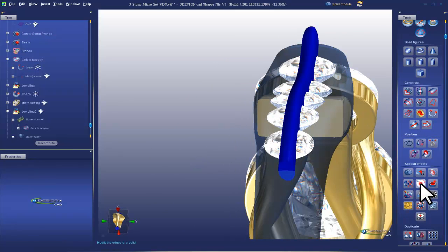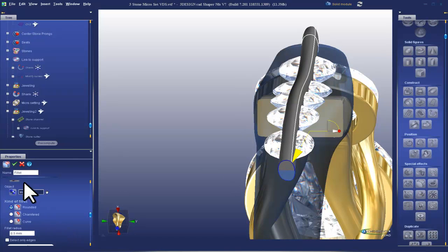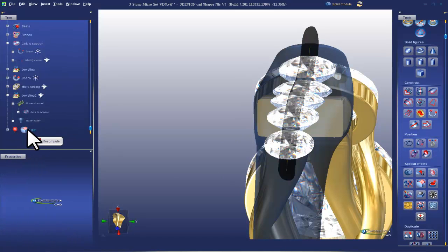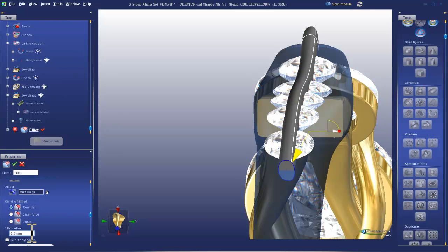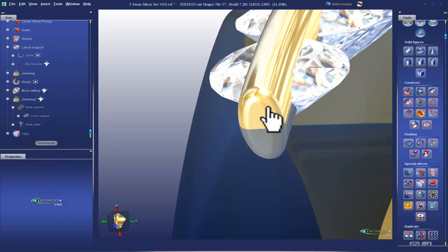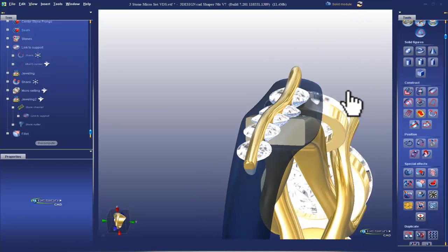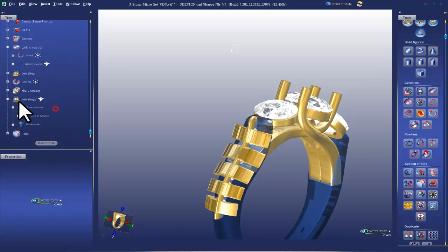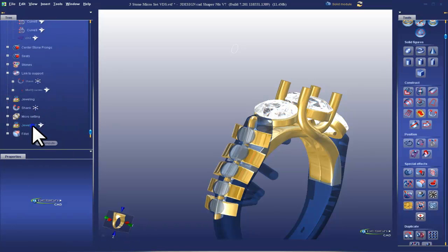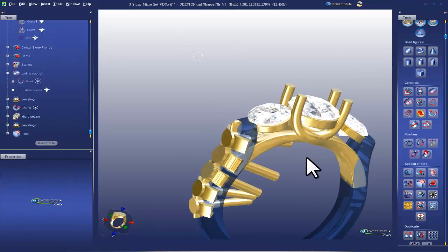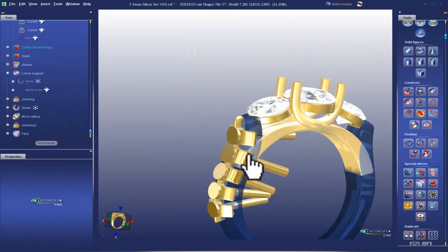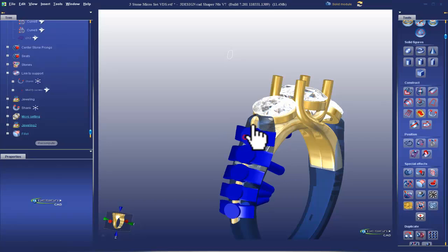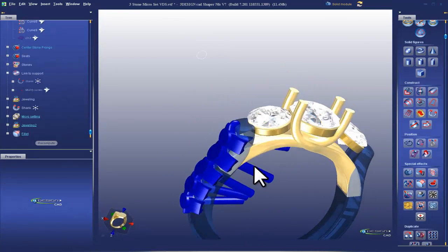And down here, I'm going to add a fillet as big as I can muster. Try 0.5. That's too big. So I'll go down to 0.3. And there we have it, a nice fillet. And that is going to be big enough. It's a pretty small feature anyhow. So these three elements, the micro cutter, the traditional cutters, and the sweep, are going to make up my Boolean cutters.